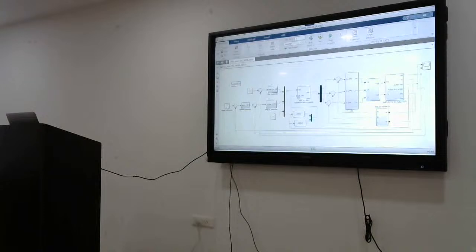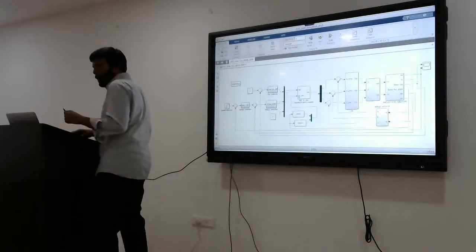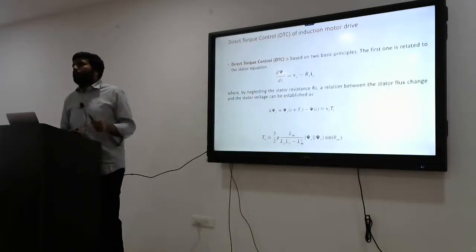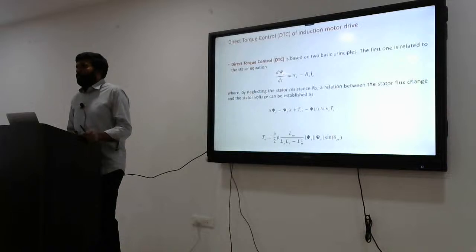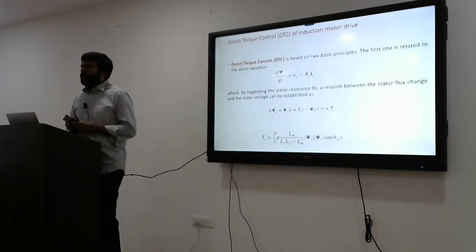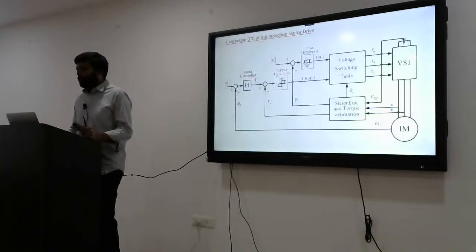So in 1983, they proposed one more advanced speed control method for electric vehicle applications, called direct torque control. The main objective of direct torque control is that, without any transformation and without any orientation, torque and flux can be controlled effectively. That is the primary objective. So by using a phasor diagram, I will try to explain this concept.